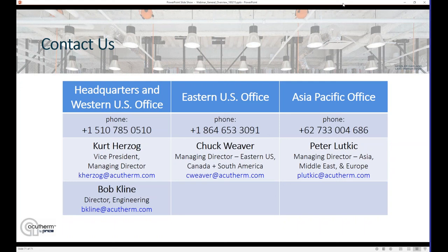So where is the Therma-Fuser diffuser applicable and where is it not? Easiest answer there is, if you're thinking a VAV system, you should really be thinking a Therma-Fuser diffuser system. If you've got something like a hospital, at least here in the US, hospitals require room pressurization and air changes per hour requirements, not a great application for VAV. Also not a great application for Therma-Fuser diffusers. But if you've got, say, a medical office building, in contrast, where you've got a lot of small spaces, doctor's offices, exam rooms, that's a great application for a Therma-Fuser diffuser system. So really anywhere you're thinking VAV, think Therma-Fuser diffusers.